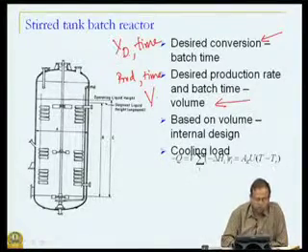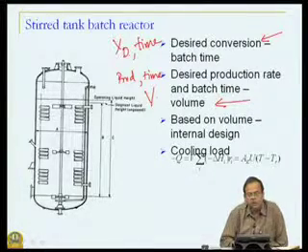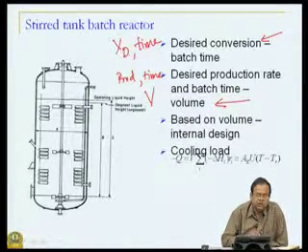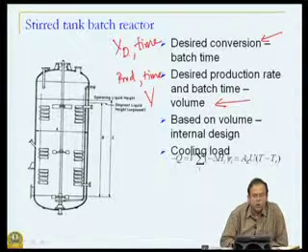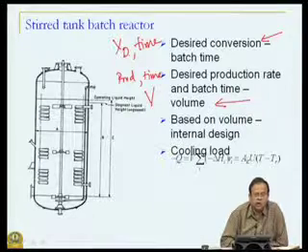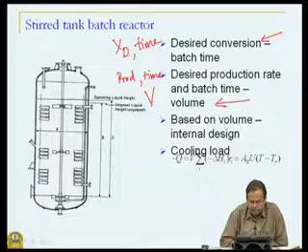Now, once you know the volume, then with either a heuristic empirical approach or, in today's age, CFD simulations or whatever you want to do, one can design the internals, that is, what should be the height to diameter ratio, the diameter of the impeller to diameter of the vessel ratio, clearances, baffle sizes and so on.